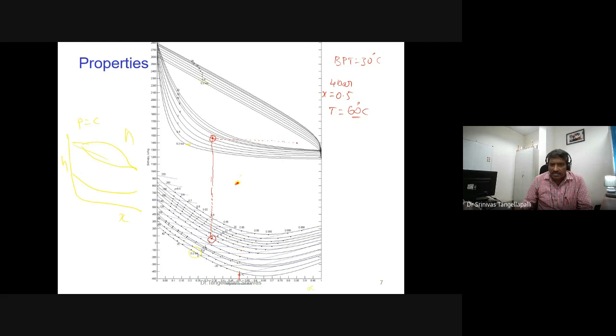Where do I have to stop here? The saturated vapor curves are too close: 0.2, 0.4, 1, 2, 4. I think this is the curve. It's at higher concentration, and the closeness is increasing. I can say approximately 99%. Ammonia concentration is 99%. Then what do we have to do?